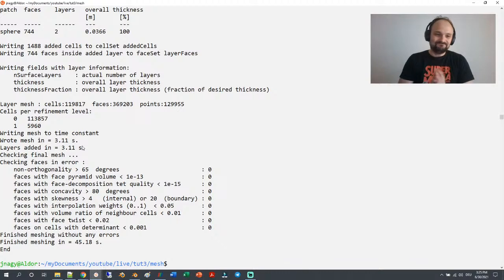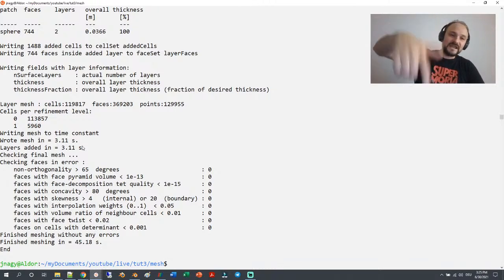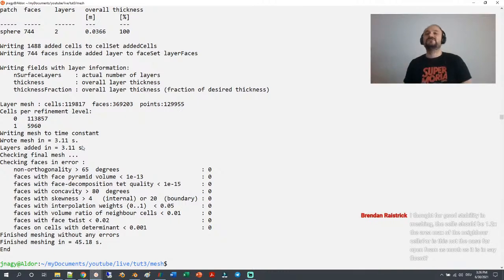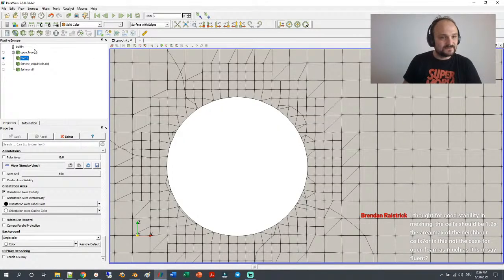We can think about the Courant number, but currently I do want to start with the laminar case, so I don't worry about it and we can use a coarser mesh. But with time, this is why I want to establish a workflow, possibly set up an Allrun script, which then creates the mesh automatically, copies it to the case and starts the case, because possibly we will need different mesh resolutions for the different Reynolds numbers. So we'll see.